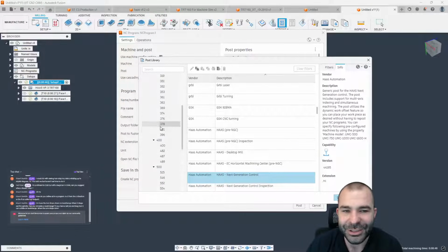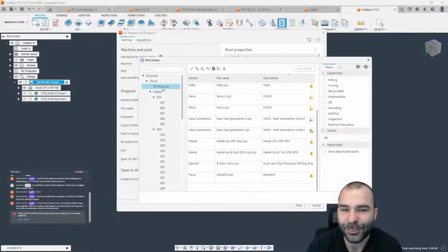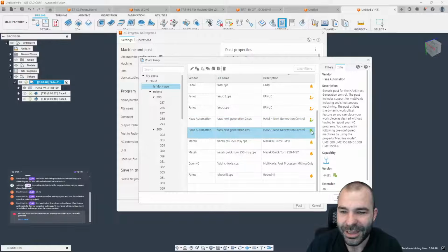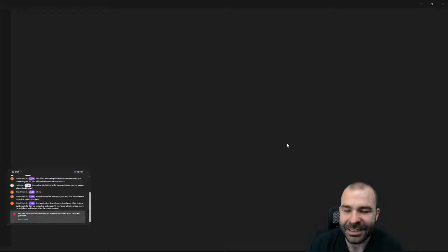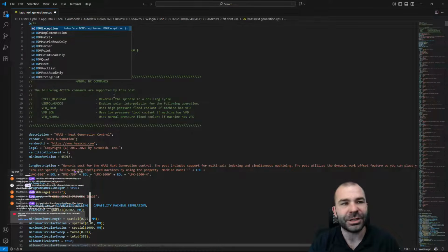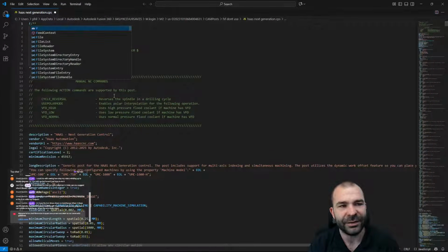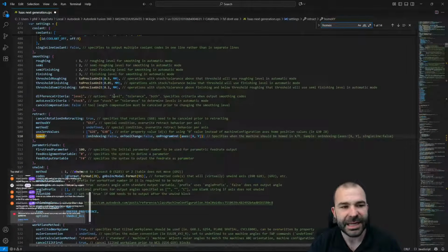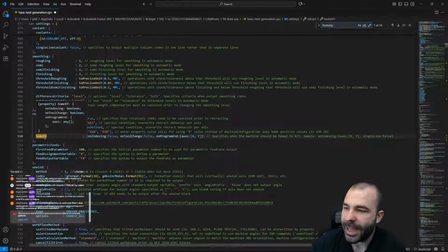We're going to go ahead and jump into none other than the place where we have tons of post-processors for me to ruin. And as you guys are going to see here, we should have one right here. Let's go ahead and edit this. And what I'm looking for, simple enough, if you just use a little Control F, as in Fox, we're looking for home, and then you could say XY. So as you guys are seeing in this line, we have home XY.